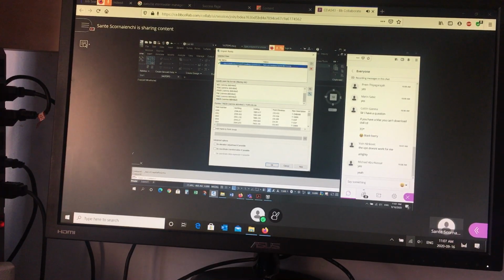So now I know where my data is coming from. I know the file format for that data. Ready to go. And it gives you a bit of a preview here: point number, northing, easting. But it's hard to tell just by looking at the numbers which is the northing and which is the easting. So just pay particular attention to this. That's all you want to do at this point. When you say OK, it'll import the points. So I'm going to do that.